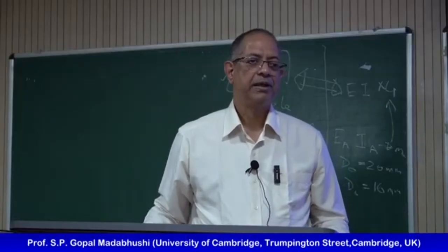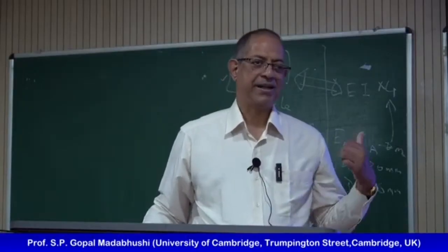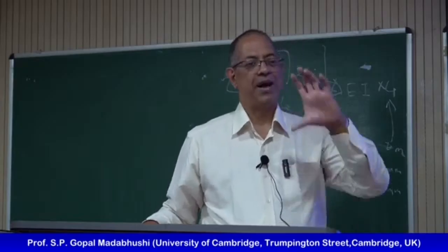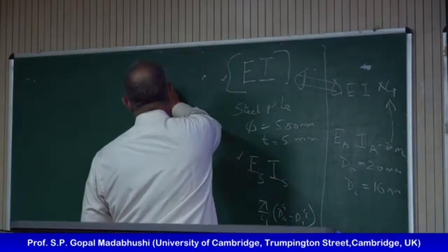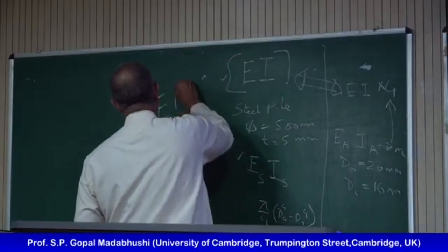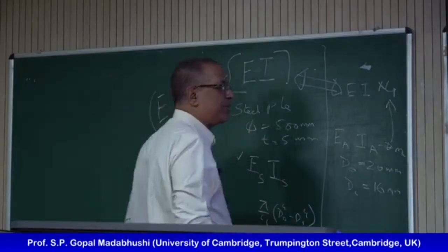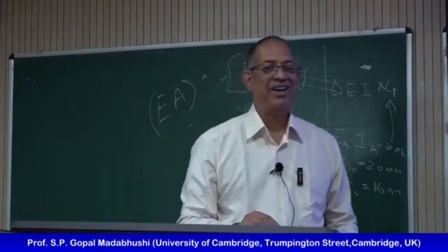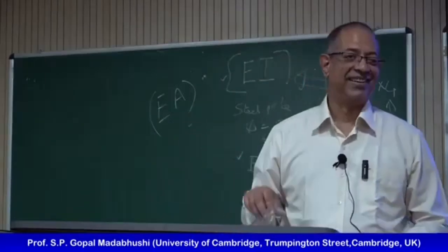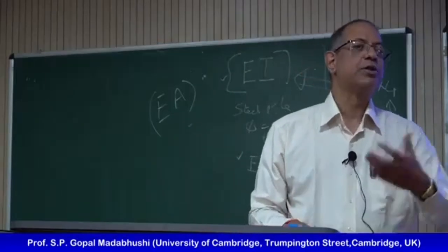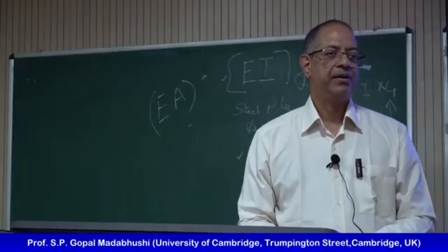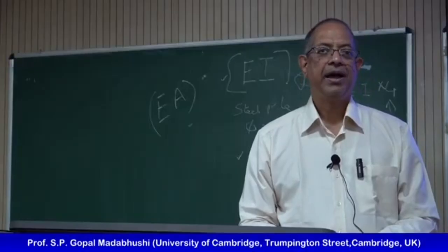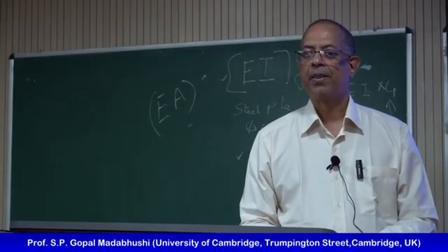For flexural rigidity, we have to match that. Similarly, if you want to match the axial stiffness, you do E times A. Look, you can't do centrifuge modeling not knowing mechanics, but these are easy, right? So we can choose the material, choose the section to do that matching. Straightforward.